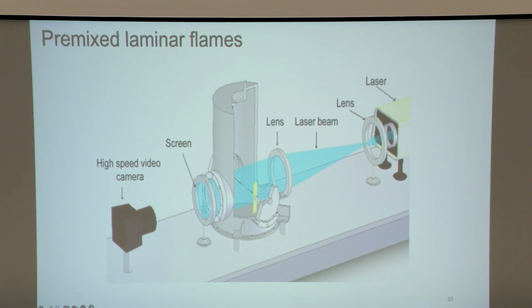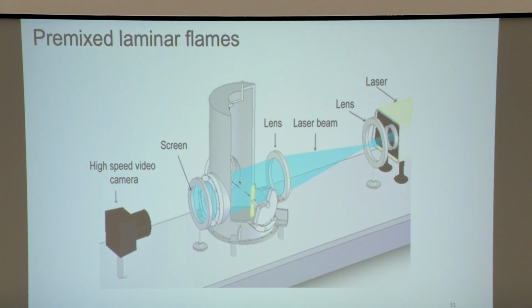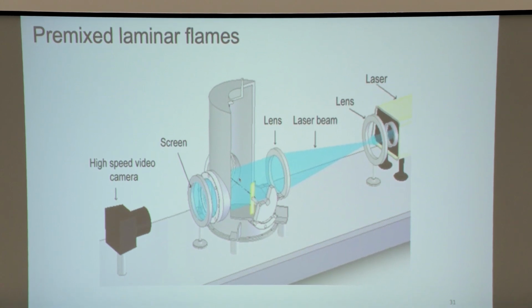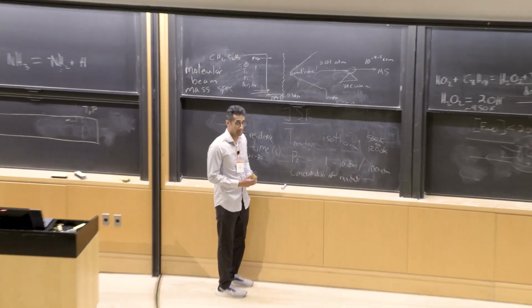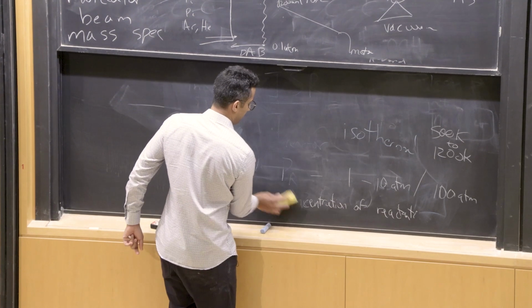So here they just take a chamber, and inside of the chamber you put a fuel-air mixture, and then the chamber has some windows, so you can do diagnostics. I think in this case, they can do simple things like Schlieren imaging. And then the gas mixture is ignited with a spark. And then you have what we call a spherically propagating flame. Yeah? And that's how you measure the flame speed, in these types of chambers.